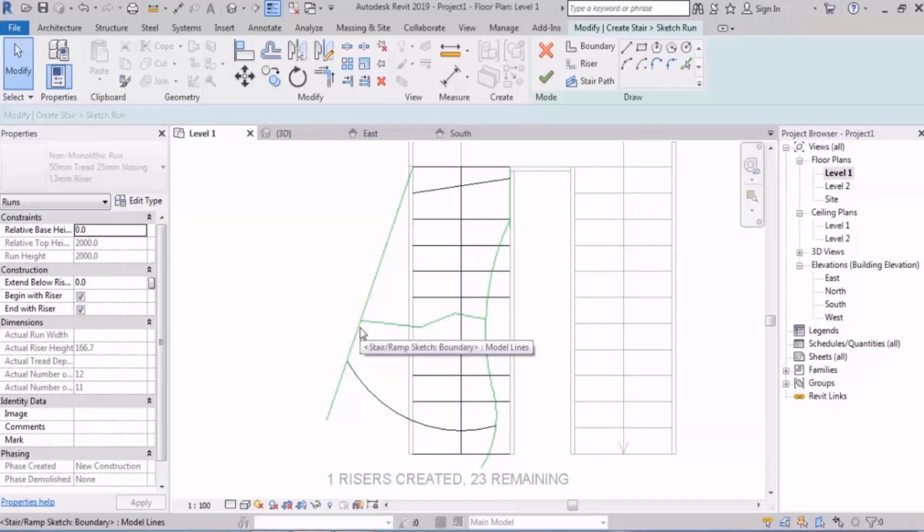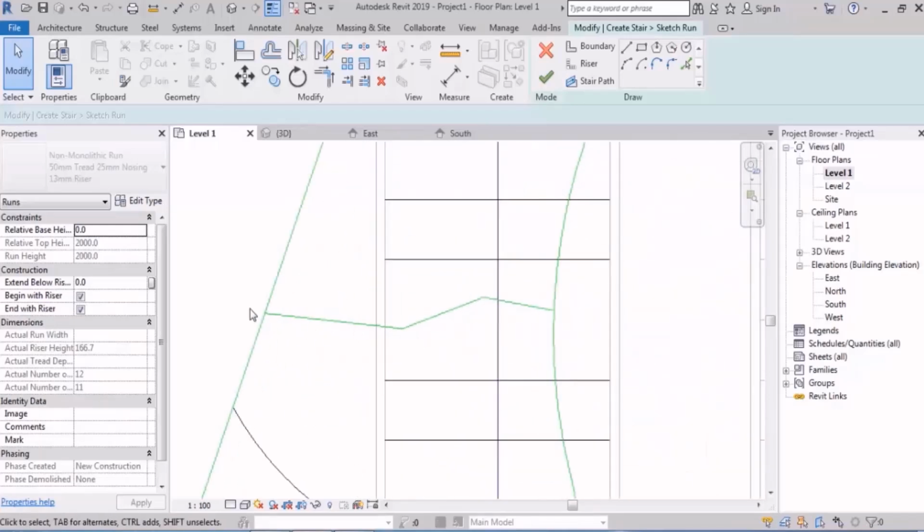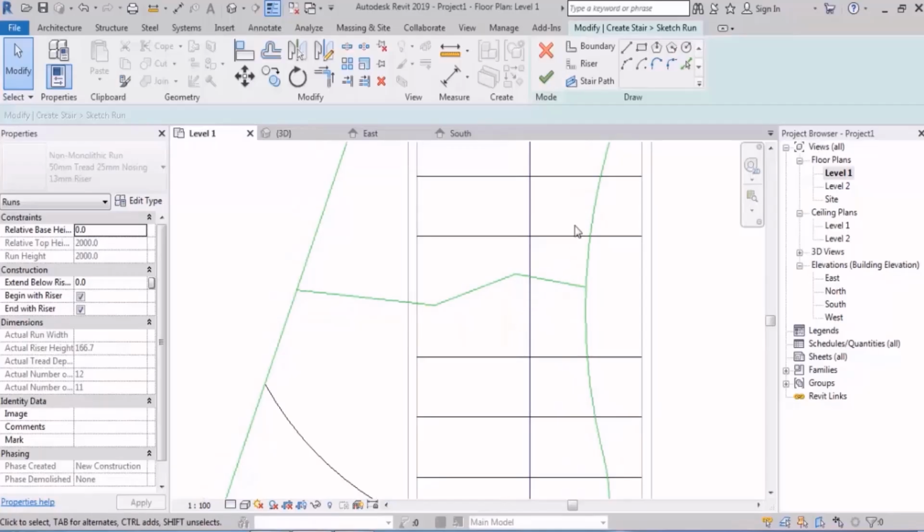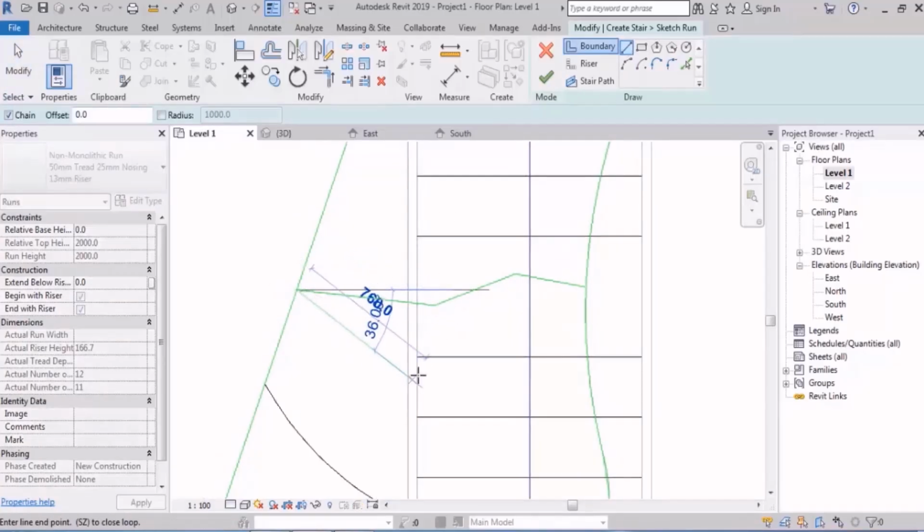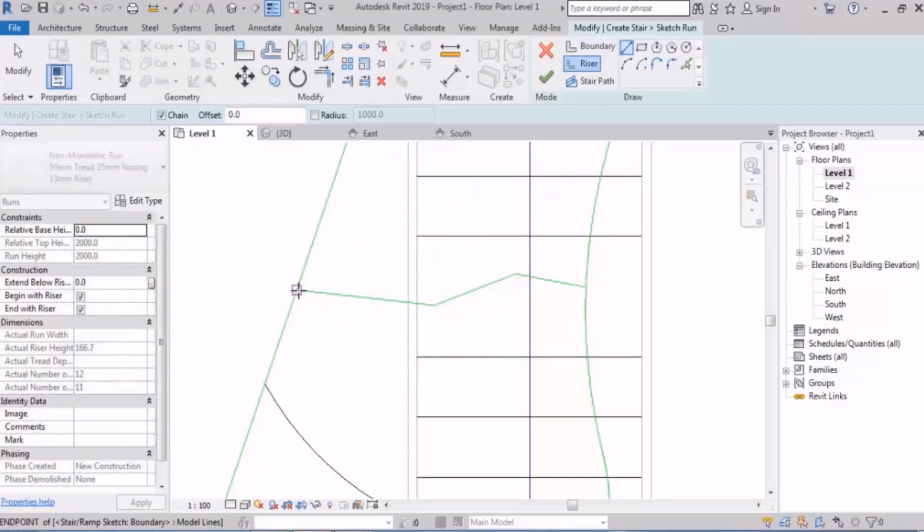The second point, we cannot pass the boundary. Now if we climb the stairs, we will pass the boundary in the middle. So this is wrong. It must be what? That's right, it must be a riser. Now, is it possible to change this to a riser? No. But there is something you can do, and that's to draw on it. Oh, I'm drawing with boundary.